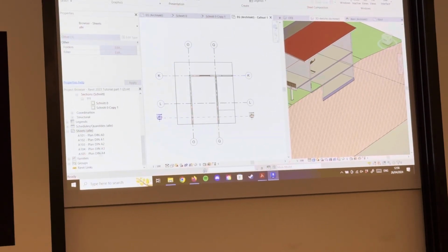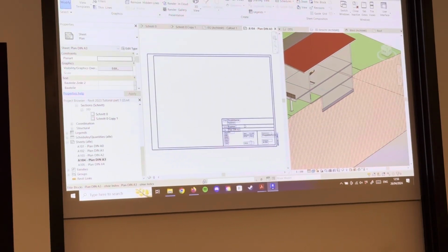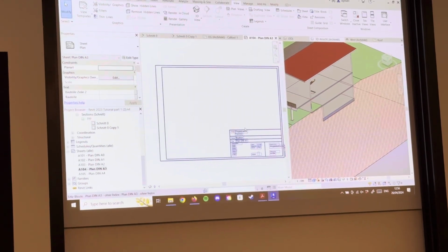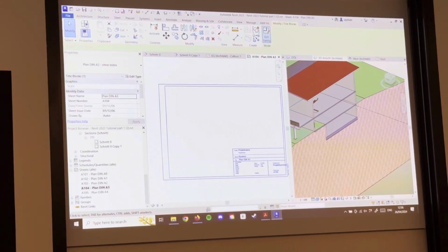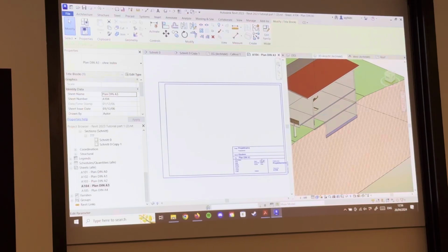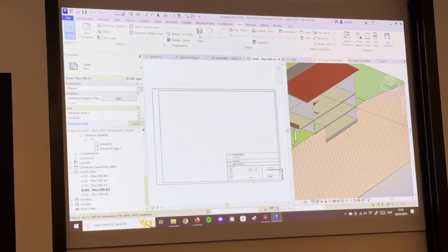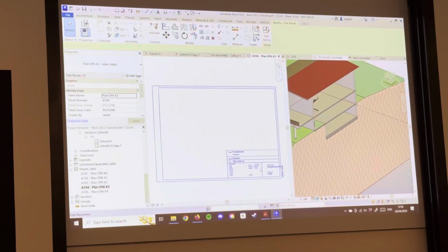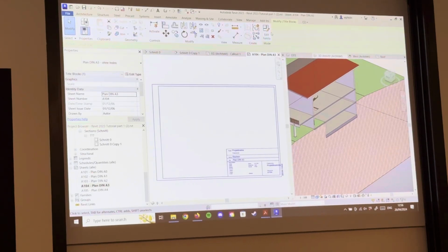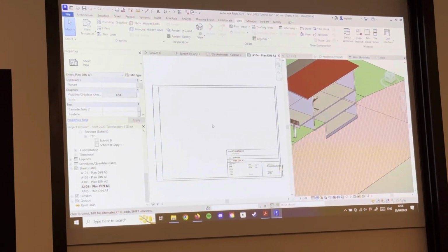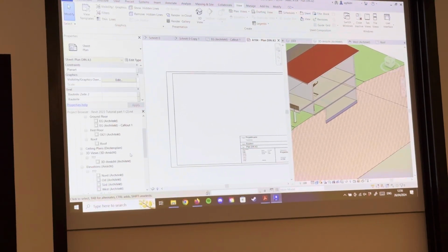And in this case, I don't need to load one since we already have some created. We can just open one of them. And then you can edit it by double-clicking on it, or edit family, and delete the stuff that you don't really need. Due to time constraints, I wouldn't edit it. I can just show you where to do it. You can do it here, edit family, and then delete some stuff that you don't need and then go back.